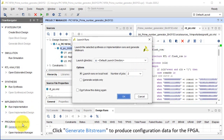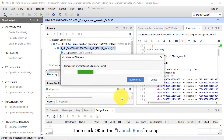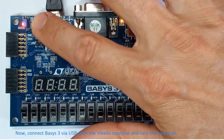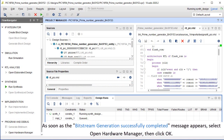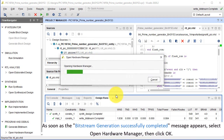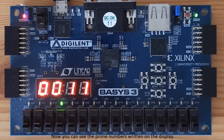Click Generate Bitstream to produce configuration data for the FPGA. Then click OK in the Launch Runs dialog. Now connect BASYS3 via USB with the Vivado machine and turn the board on. As soon as the Bitstream Generation Successfully Completed message appears, select Open Hardware Manager, then click OK. Now you can see the prime numbers written on the display.